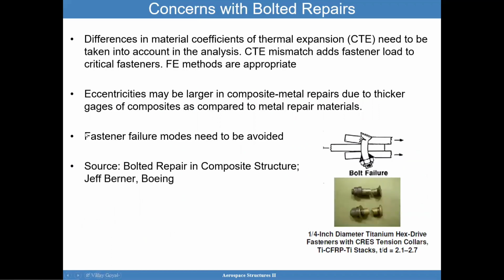Differences in material coefficients of thermal expansion can be an issue for both of the repairs and should be considered in your analysis as well. Eccentricity may be larger in composite-metal repairs due to the thicker gauges of the composite. Fastener failure modes need to be avoided.